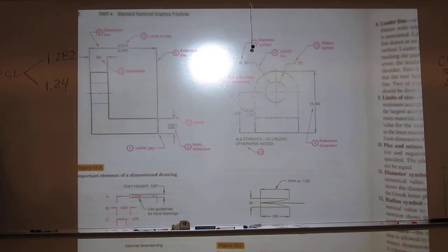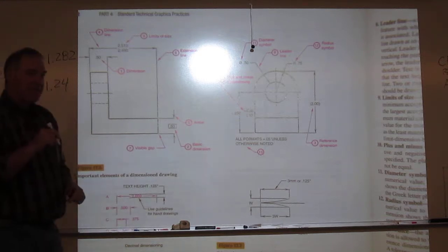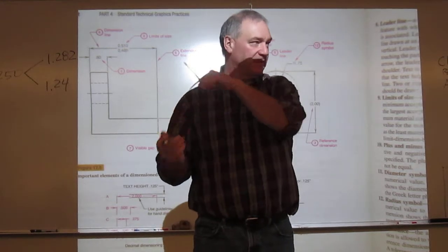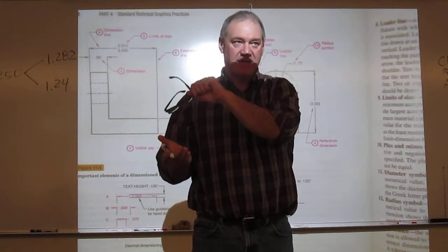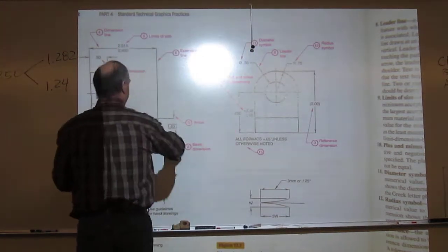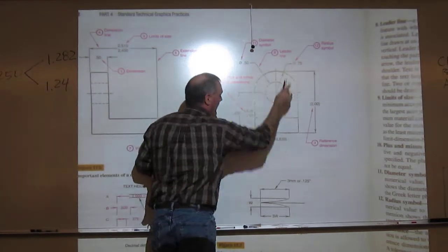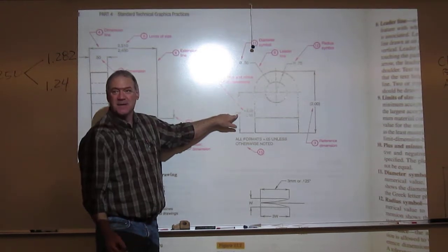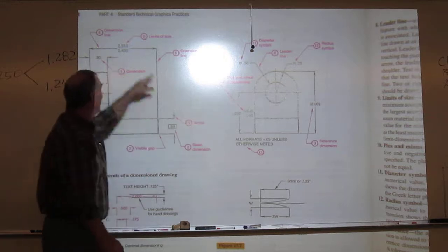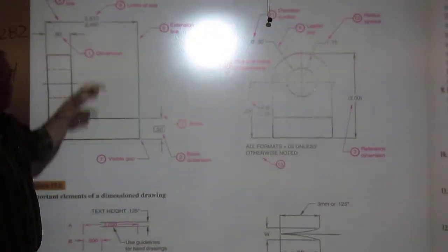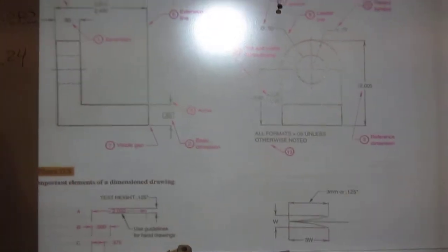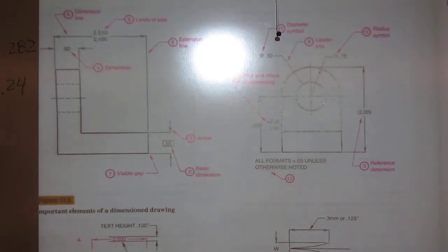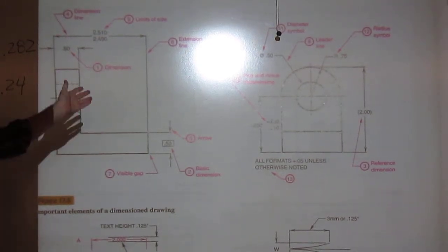Keep in mind that we have general notes. I asked you to put a general note that said all dimensions plus or minus 0.02 inches, and this should sit down in the bottom right hand. Now when I say that, that applies to every single dimension out here. So it applies to that one, that one, that one, all of them, except for this one, because we took the time to do something different here, and that one. Here we're removing that general tolerance off of those, and we're applying a direct tolerance. General means applies to the drawing as a whole, direct to the one dimension.